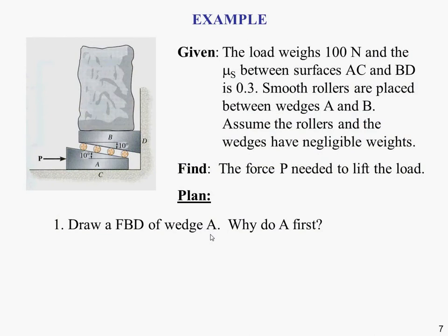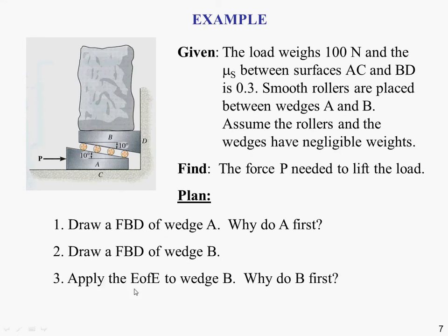Okay, so hopefully you've had a think about that. The reason that we do the free body diagram of wedge A first is because that's where we're applying the load, that's where we know the impending motion, so that makes it easier for us to draw the correct sense or direction of the friction forces.